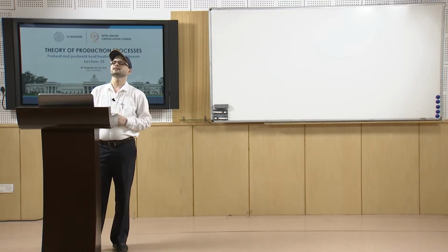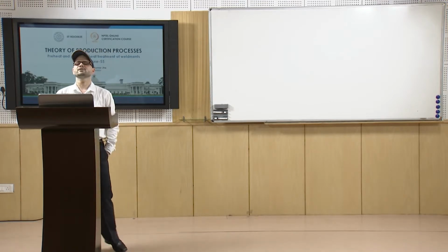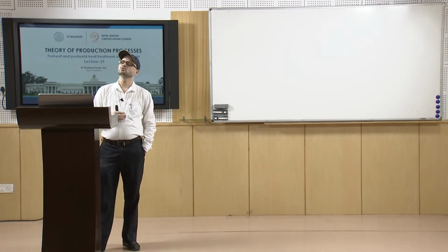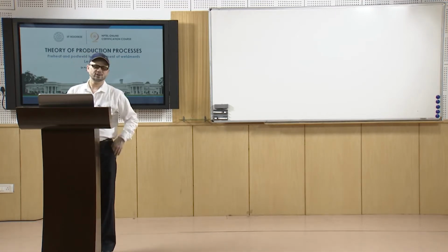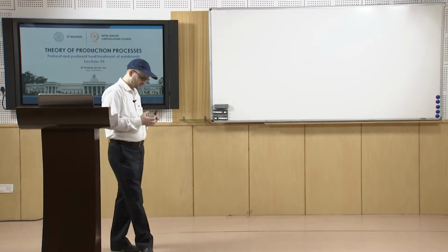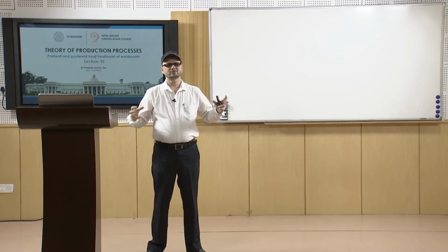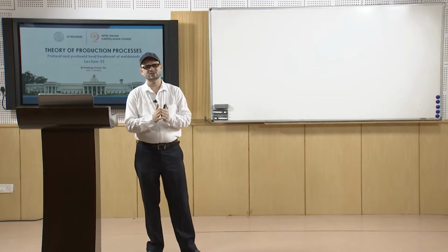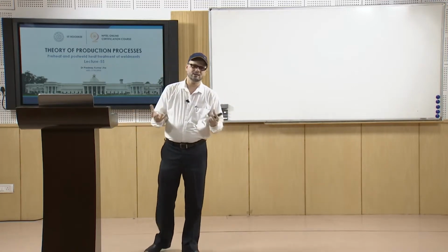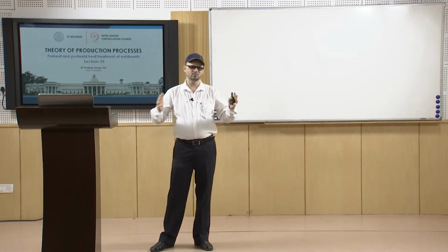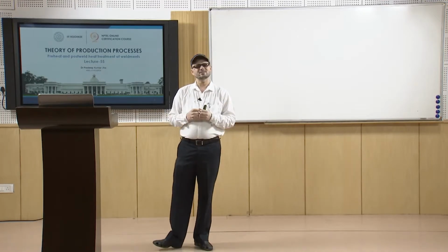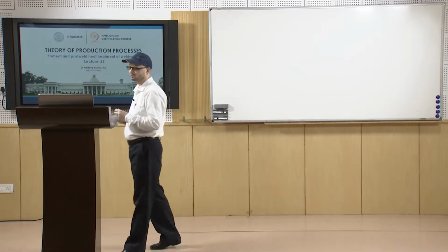In those cases you need a preheating temperature of about 100 to 200 degree centigrade, because in the case of heavy sections, the weld pool is surrounded by, or adjacent to, the thicker parent metal on both sides, so the heat extraction rate will be quite fast.